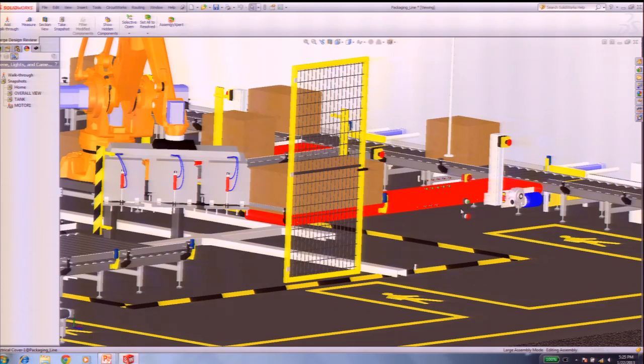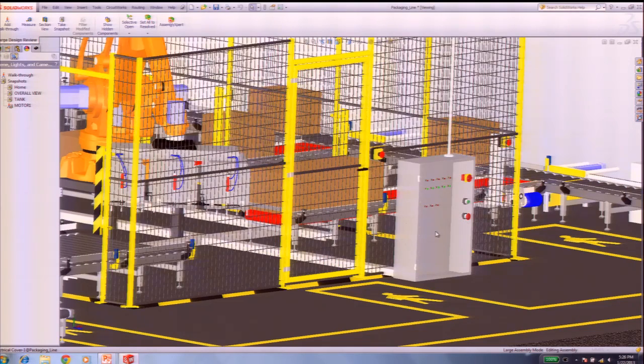And bring it back? Yeah. If you change your mind and want to bring it back, you say, okay, my control unit is approximately here, and I bring my cursor to where it was and hit Shift Tab, and I can start to bring things back in this fashion. Like that. You have to bring everything back sequentially. You can't skip some items. You have to bring it back in the same sequential fashion that you hid it. Okay? So more questions? Yeah, Joe?